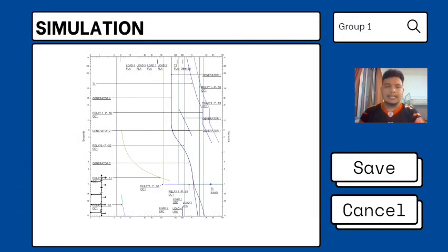For this IDMT graph, as we can see, the IDMT relay standard is a minimum time relay. The time of operation is inversely proportional to the magnitude of the fault current near the pickup value, and becomes significant when slightly above the relay pickup value.